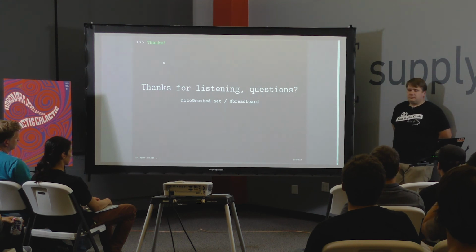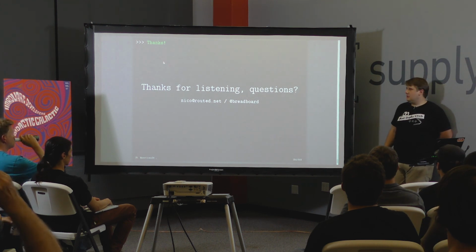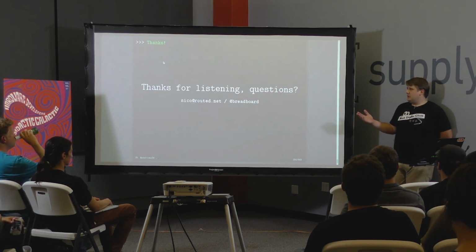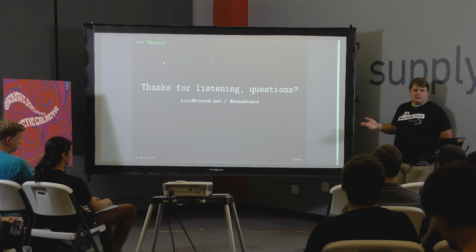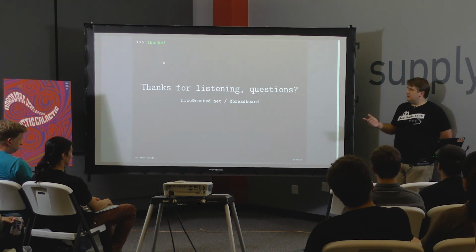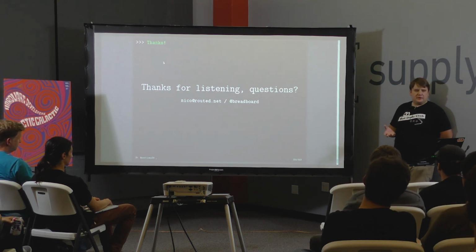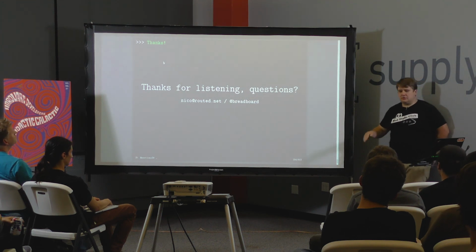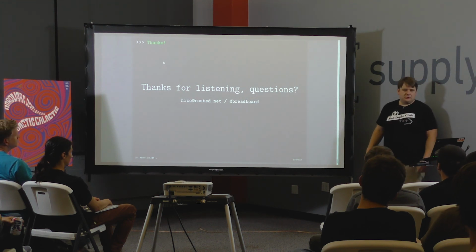We don't really get a lot of interference from cyclical or repeated noise, but we'll have effects like lightning and some other discharge. And then you also have a concept of antenna temperature. Depending on whether your communication system is facing towards the sun or away from the sun, you can get different background noise levels, and that's kind of like a Brownian motion.